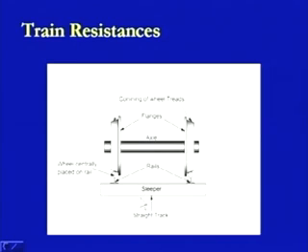Here in this diagram, we are looking at the straight track condition, where this axle is placed along with these wheels in the equilibrium condition on these rail systems. Here we see that in both cases, the average diameter is on the rails, and when the average diameter is on the rails, it means the total distance traveled by the outer wheel and the inner wheel is the same, because this is related to the circumferential movement, that is pi into d. So the distance moved by this wheel as well as by this wheel is going to be the same as we are talking about a straight track.